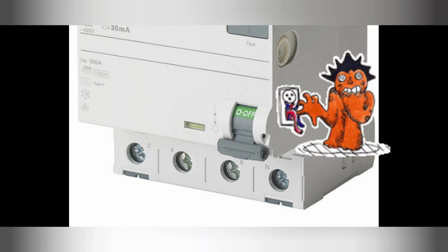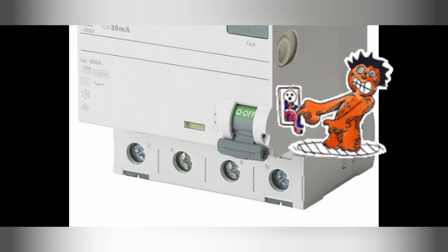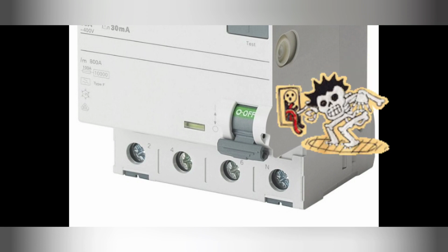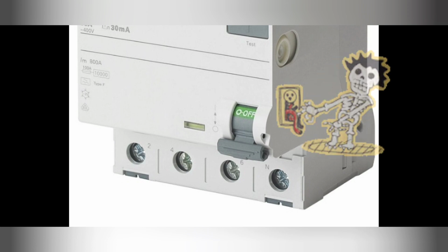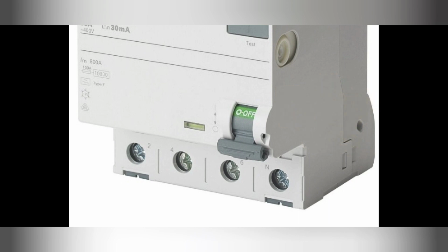So let me go back to what I was saying. The side note is that that will cause an electric shock. Once you touch a live circuit and you complete the path to ground, you will get an electric shock. Worst case scenario, be electrocuted. Okay, back to what I was saying. Once you have a person coming in contact with a live circuit and they complete the path to ground, you will also have residual current flowing, right? So that is also leakage of current, and residual current is flowing, and that is also a ground fault, right? Speaking of ground fault,